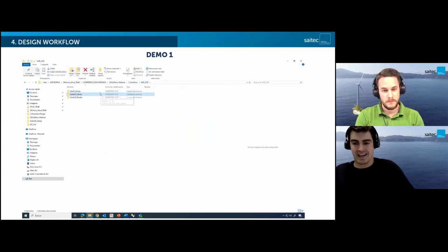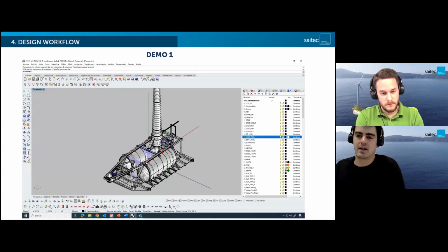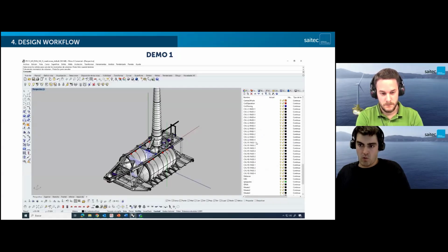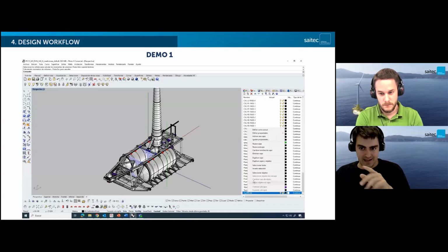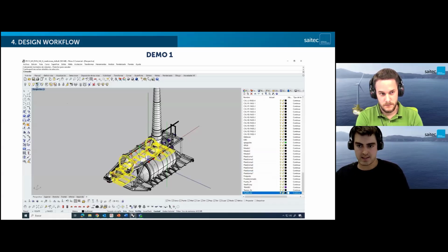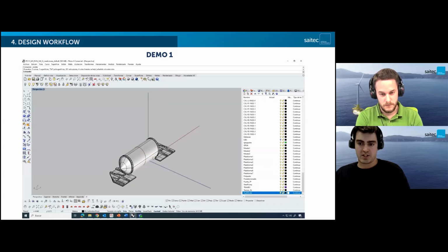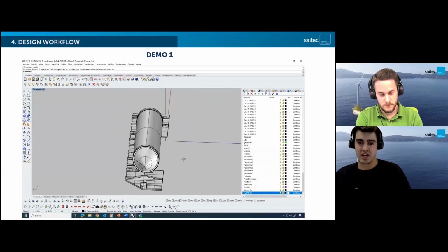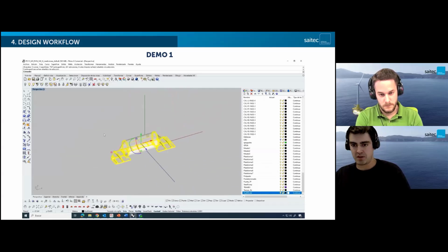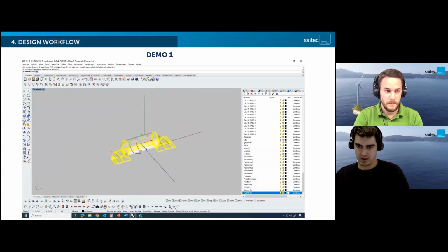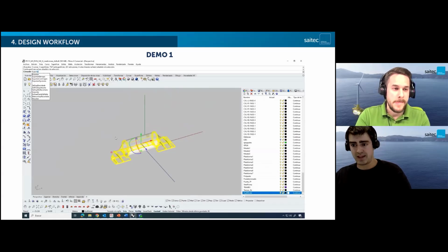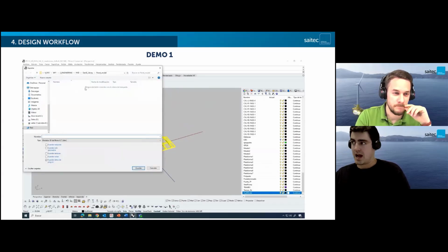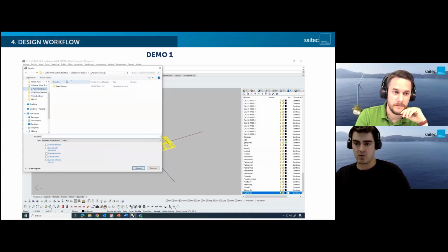So the last thing that we need is the external geometry. So if we come back to the model and select the specific layers. So here is the hull model, which at the end are the floater and the plate. We only export half of them, as in Genie we are able to apply this symmetry to then have all the platform. Worth mentioning that here we really don't need volumes, as we're only interested in the shape of the body. So there's no need to have a closed polysurface for the volume.